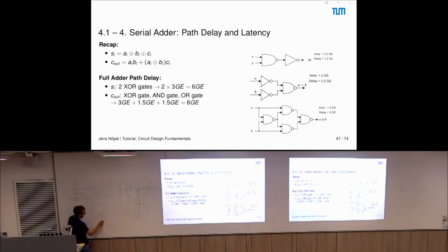So you have your AND and CI, and those two end up in an OR gate building Cout, right? Can you see it? Okay. So this is the gate logic of how you could build up this function. And I hope now it's obvious why we only have 3 gates here, because the critical path here is only this one, right? And this one just happens in parallel, right?